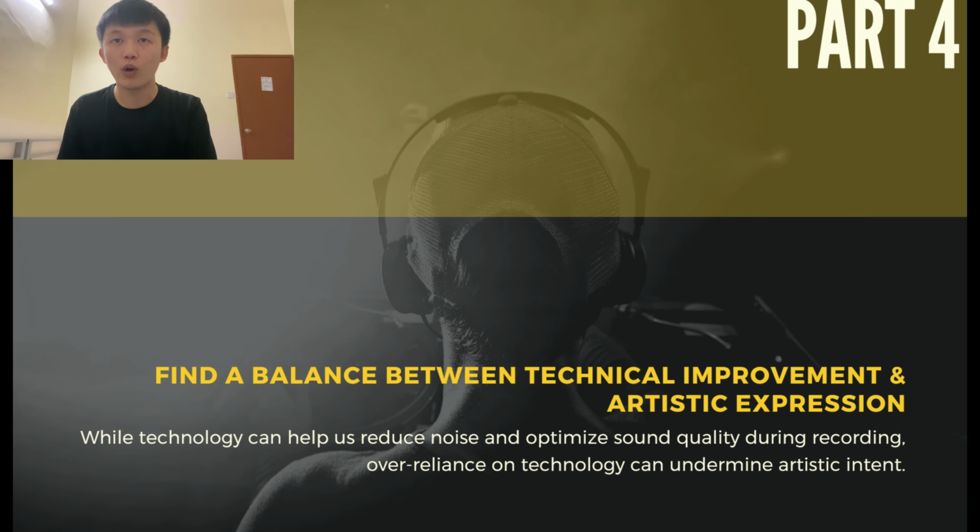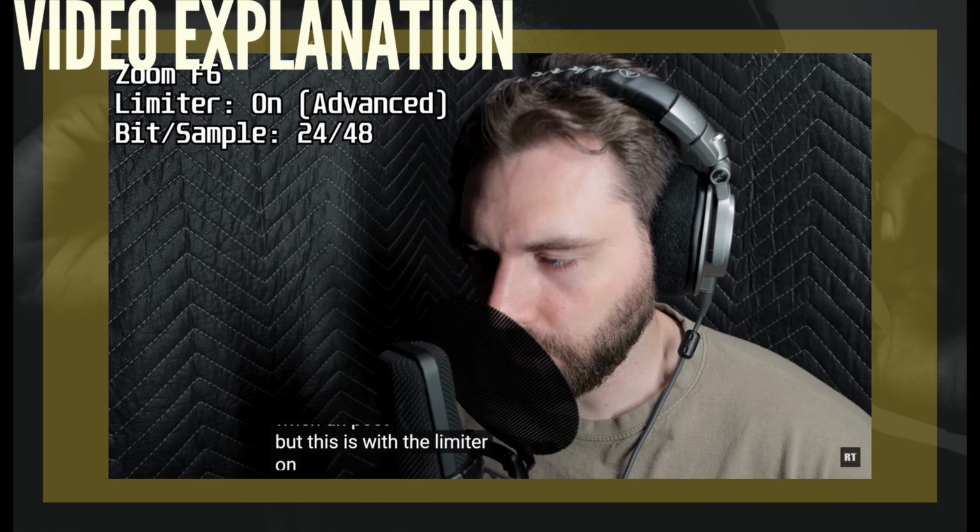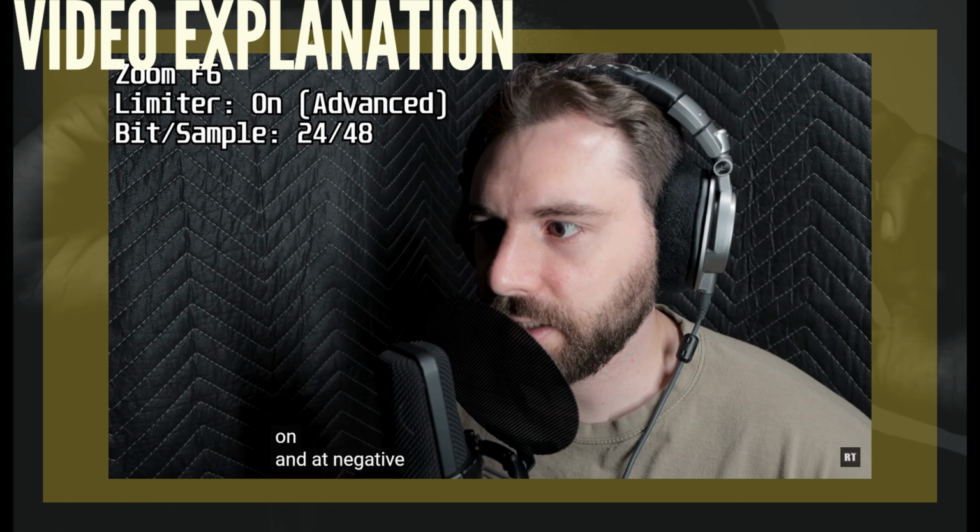For example, when we use a limiter, it can prevent sound overload, but if it is set too strictly, it can make the sound appear too restrictive and lose its natural dynamics, which may not be ideal for some music or conversation recording. Put the limiter on at -4.